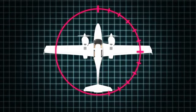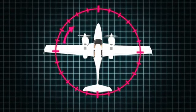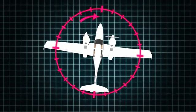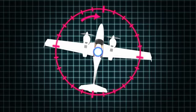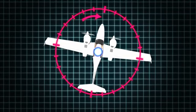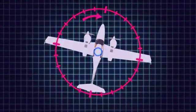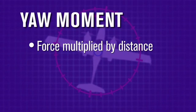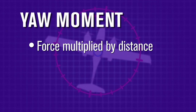Because the thrust is uneven, the aircraft will yaw towards the engine with the lower amount of thrust. This yaw occurs about the center of gravity and can be of varying magnitude. We call this yaw moment. Remember, moment is force multiplied by distance.